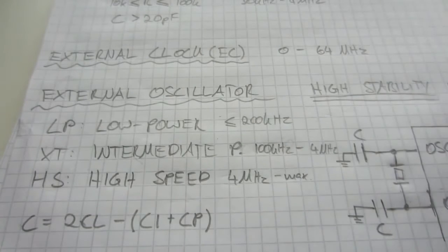So the error in the serial clock rate will be 0, ideally, if the crystal really is oscillating at the given frequency, which it isn't, because the accuracy is about 10 to 100 parts per million. Compared to the internal oscillator and the external RC oscillator, it's very high stability, but even the crystal oscillator is going to drift over time and over temperature.